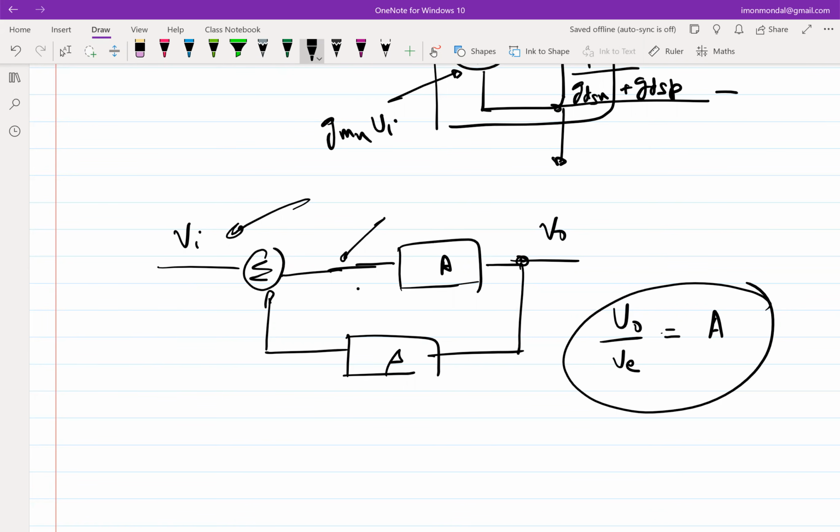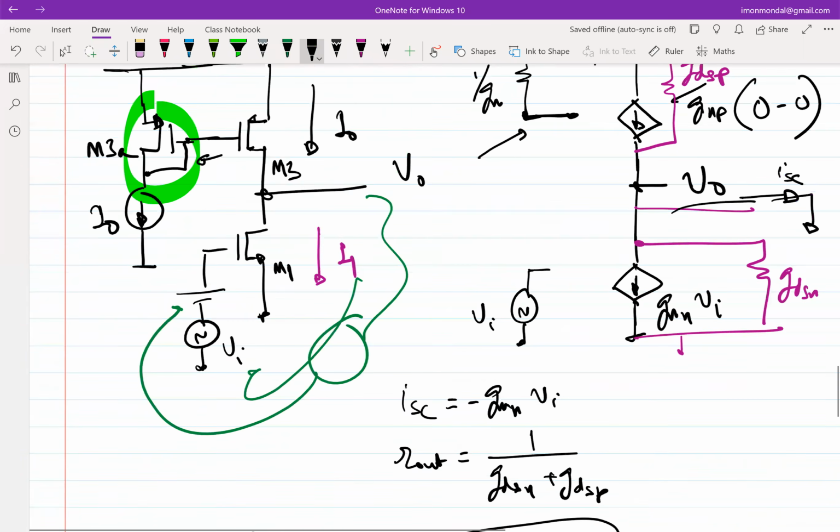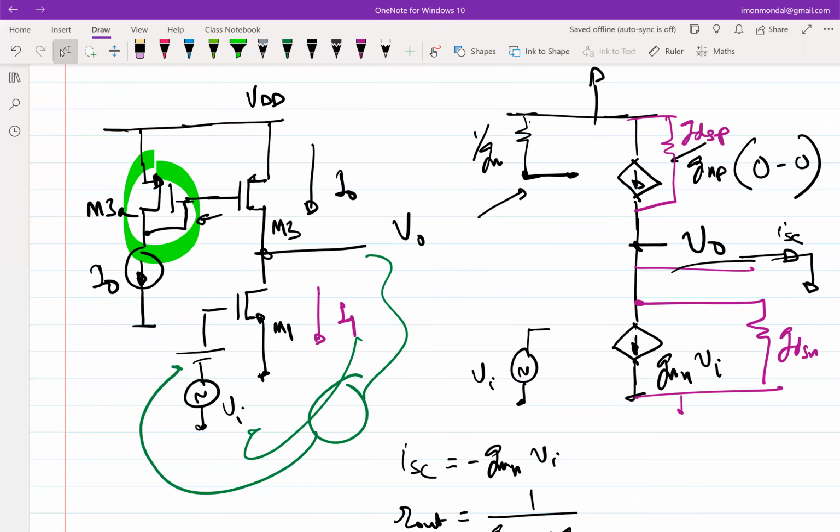Thanks for bringing it up, but this is a very common mistake that I have seen students make. They think that I have put in negative feedback, so the gain has gone down. Yes, gain has gone down, but not between the nodes that you were looking at. From your actual input to your final output, yes, the gain has stabilized, it has gone down, fine. But your actual input is no longer the input of the amplifier.